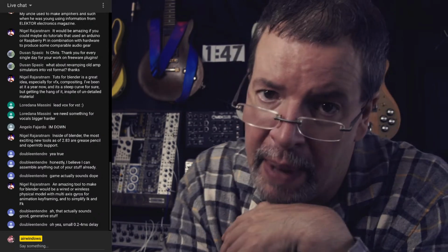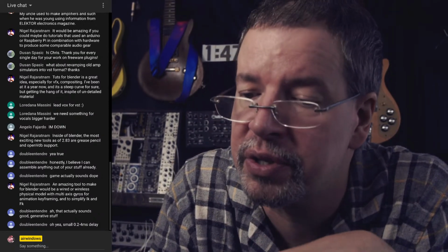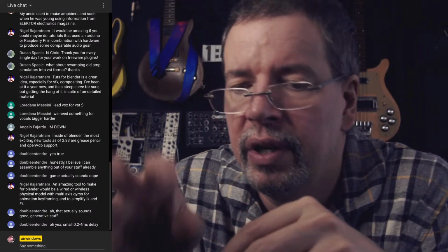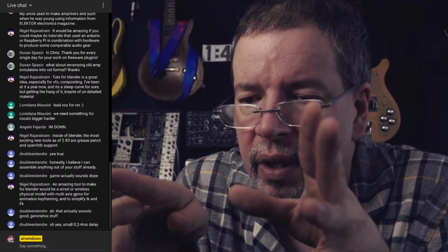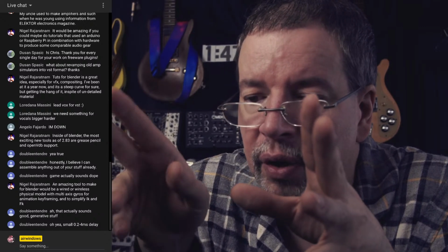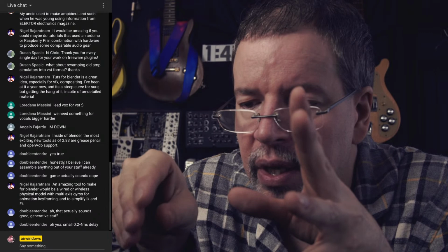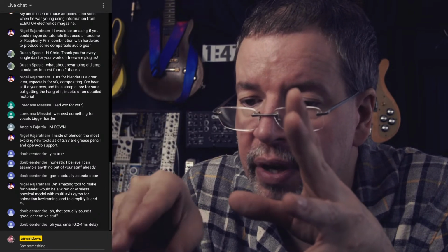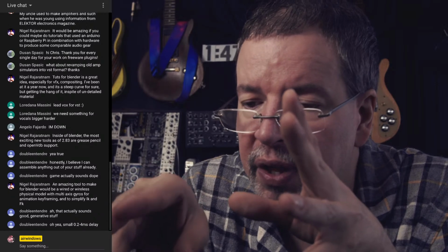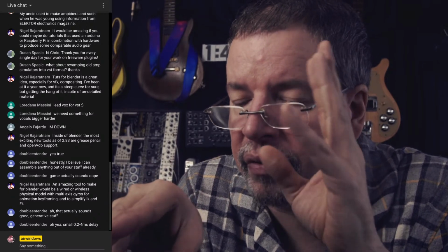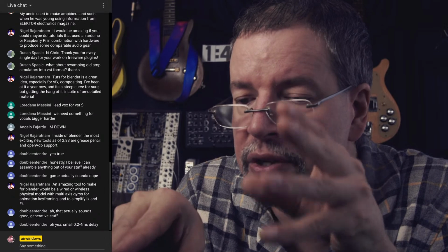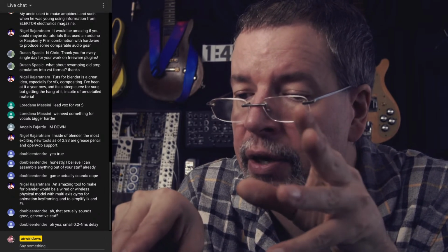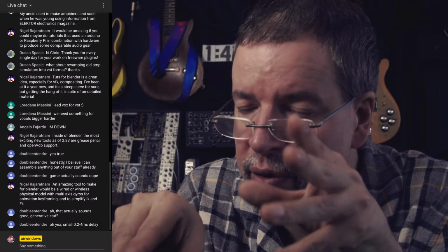So what I did was I patched them into each other's CV inputs so that if this one here was generating a lot of notes, causing the CV voltage to be high when the notes were being generated, it would also put that voltage to the CV input of this one, which has the result of turning up the knob and making it not apply any more random notes.